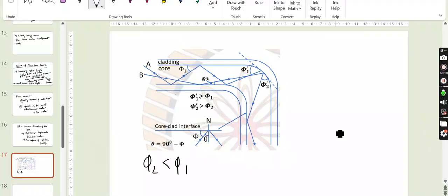It is therefore very likely that a part of light belonging to a higher order mode will leak out through the bent surface. They will leak out from this bent surface of the fiber, and most likely such a phenomenon will not occur for the TM00 mode. Clearly, therefore, a higher order mode will experience greater bending loss than the lower order mode. The sharper the bending is, the greater the loss will be.